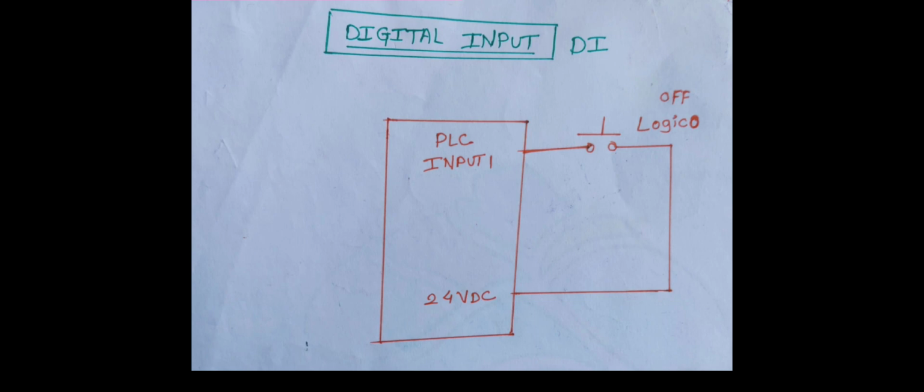It means a digital signal is a signal that exists in one of two states, that is high and low, open or close, on or off. It may be through sensors, meaning any devices in the field. How can we know whether it is active, on or off? From this digital input signal, we can see it on the DI card. It shows the on/off status as well, open or close status. The digital input output device is the hardware that sends and receives these digital signals. Then DIO devices are usually built around simple relays.